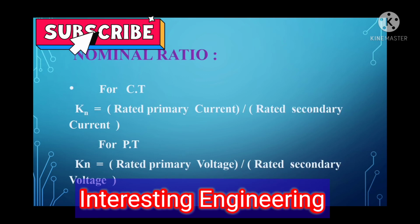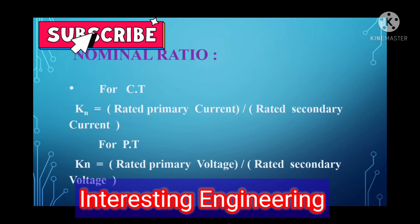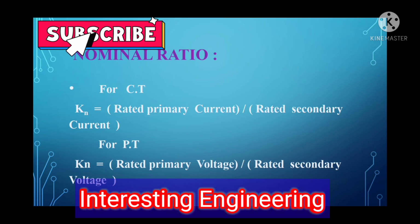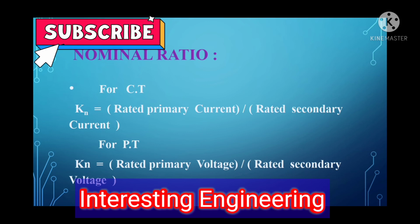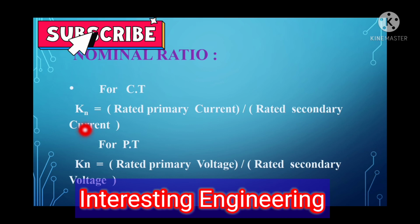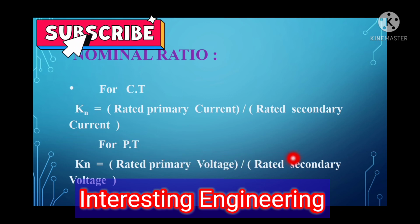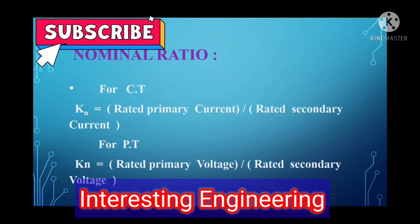The next ratio is the nominal ratio, and this nominal ratio will be represented on the panel of the instrument transformer. In any instrument transformer, the most important ratio described on its panel is the nominal ratio, and it is represented by K suffix n, and it is equal to rated primary current divided by rated secondary current. And for potential transformer, it is rated primary voltage by rated secondary voltage.